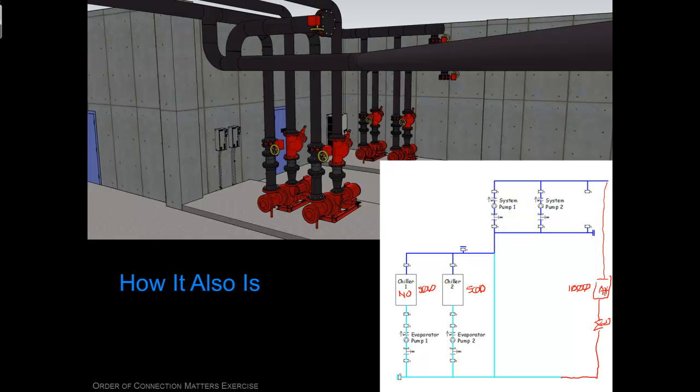So you'll remember from the first video, that's the chiller we would like to, when it ran, run at a steady load. And when this chiller ran, it's the one that has the features that let it follow the load more closely. So this is the one you'd like to be able to pick up the load swings, and this is the one you would like to run flat out when it ran.